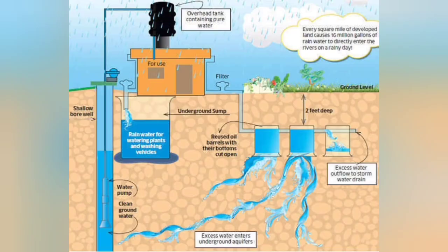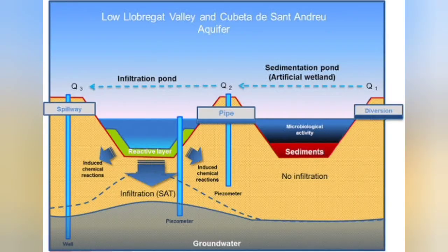Maps providing information on regional hydrogeological rock units, their groundwater potential, the general pattern of groundwater flow and the chemical quality of water in different aquifers are necessary. Satellite imagery maps provide useful data on geomorphic units and lineaments which govern the occurrence and movement of groundwater.